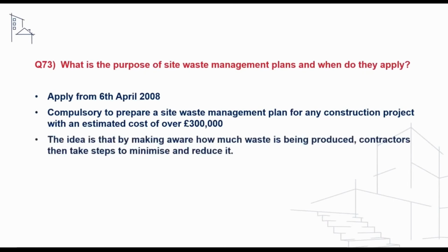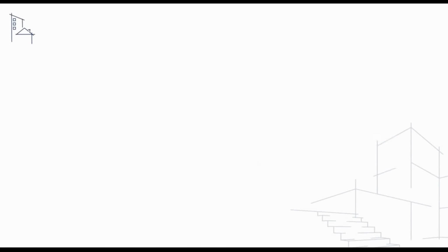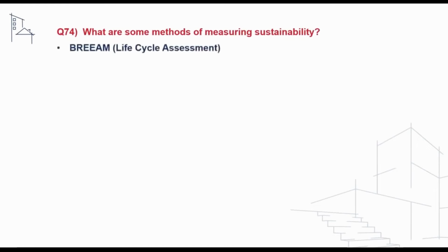And the concept is that by making us aware of how much waste is being produced, contractors can then take steps to minimise and reduce that waste. The plan must be regularly updated on how much waste is being produced and recycled so that lessons can be learned. We may also be asked a question on our knowledge of the different assessment methods for measuring sustainability. And to address this, we can make reference to BREEAM, SKA ratings, LEED, and whole life carbon assessments.